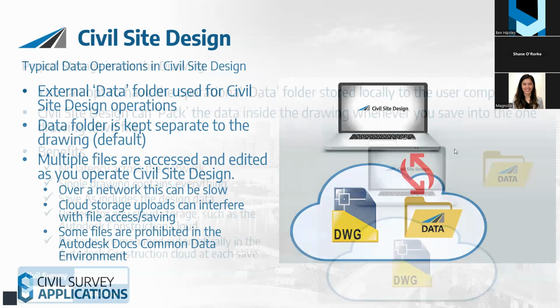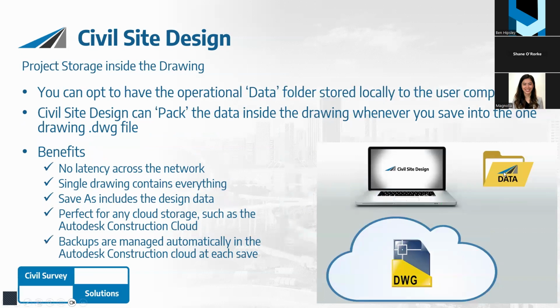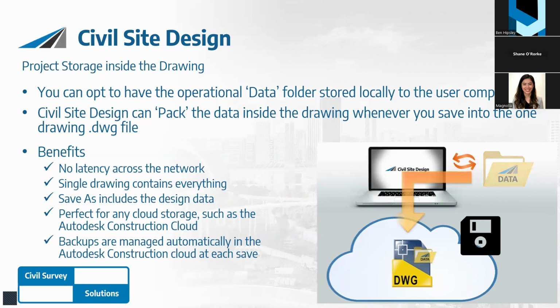So the solution is to look at storing your data outside of your cloud environment. So firstly, what you can do is opt to have the data folder stored locally. And there's just a click button. It'll go into your temp folder where you have ready access. And that's your transactional area where you're doing your work. You can also enable what we call packing, where what you do is you basically have the data embedded in the drawing every time you save. So if you think about that graphic, what's happening is when you hit a save, the software embeds the data inside the drawing and then moves that off to wherever you're saving it to.